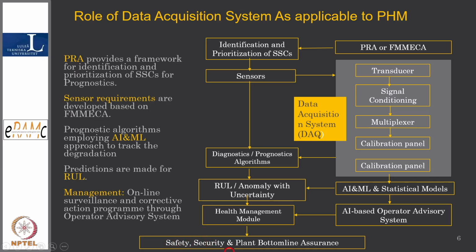And one more element that we have to address, and already at the international level, like IAEA, the International Atomic Energy Agency, they have started addressing safety and security together. So for any system built today, my probabilistic risk assessment should address the probabilistic safety assessment and probabilistic security risk assessment. Then only will the safety assessment be committed, because at the end of the day we have to keep the plant in a safe state. So both risks, security risk and safety risk, should be addressed.